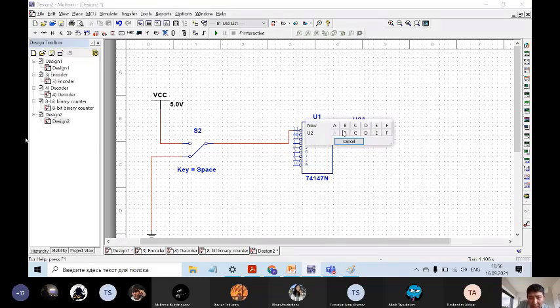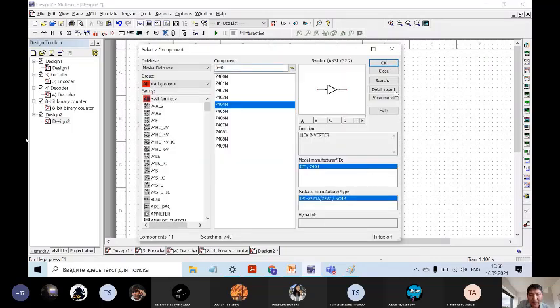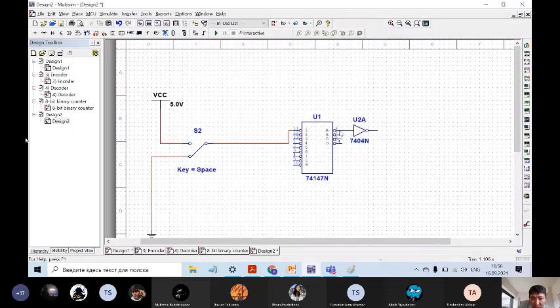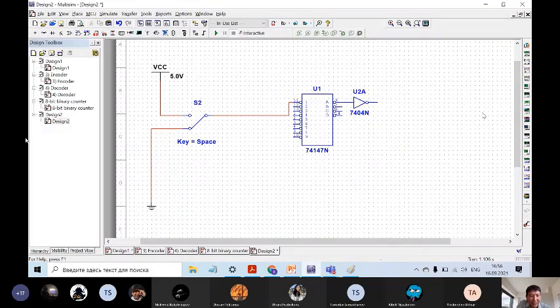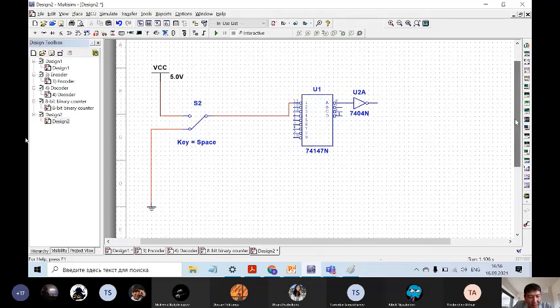So I will connect here. It means, for example, if here we have 1, output will have 0. If you have 0, output will be 1. Next you will connect the LED with a resistor to limit current, and that's it. It will be your work. But you need to connect the other switches. Okay? Do you have questions about Multisim, how to do other things? You can ask.